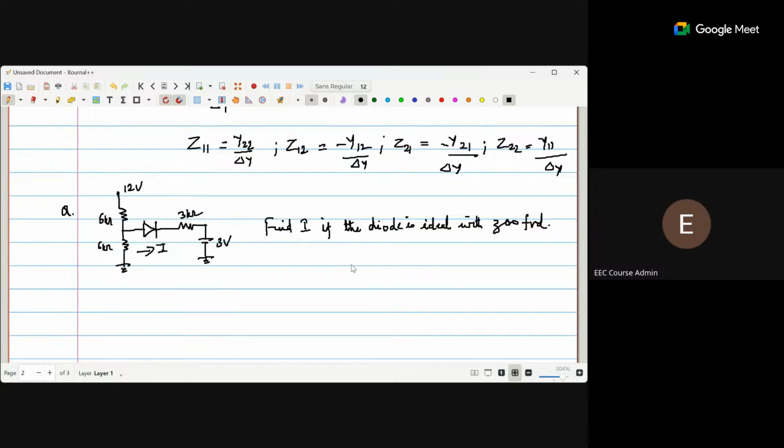So how do you get it? How do you check for the status of the diode? At the anode, ma'am. The voltage divider circuit is given, ma'am. So the voltage at the anode of the diode will be 6 volt, and at the cathode it will be 3 volt. So the diode is forward biased, and the difference in voltage is 3 volt, and the resistance is 3 kilo ohms, ma'am. According to that, we will find the I value as 1 milliampere. So clear, correct?